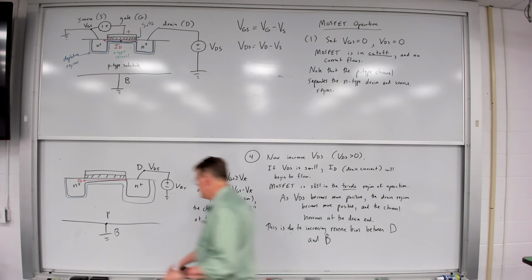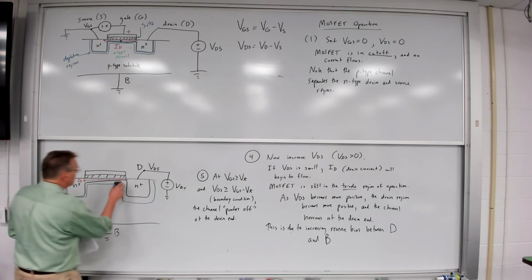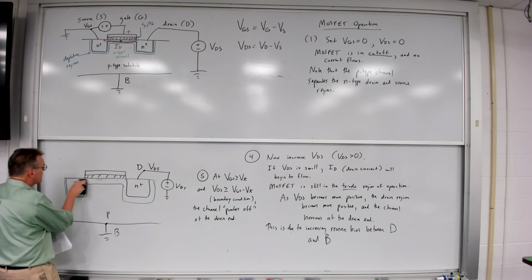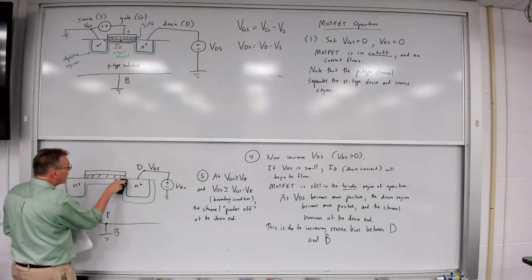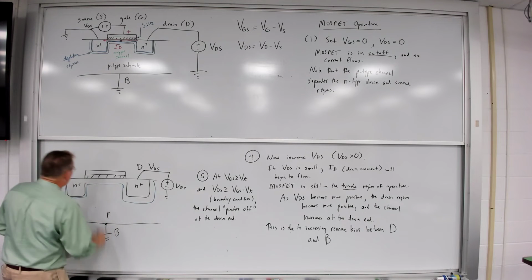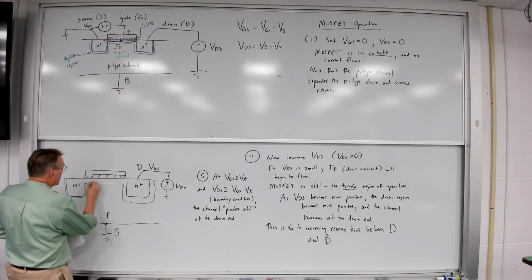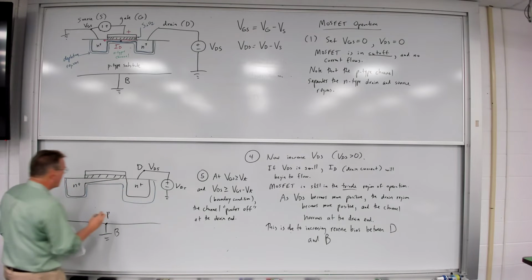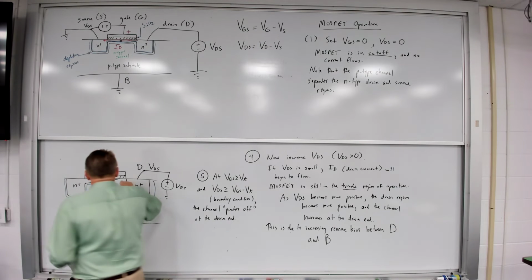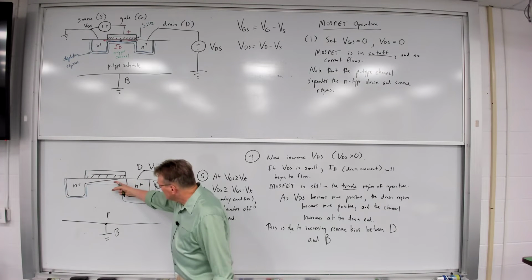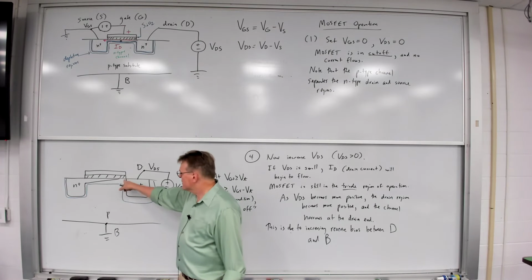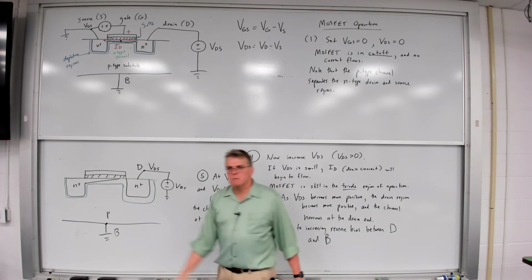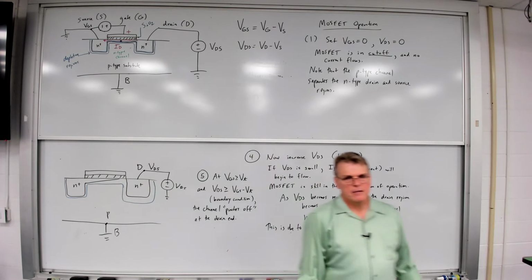So now I'm in this situation here. Now I've got this. So I get this pinch-off region where literally it pinches off completely at this end, at the drain end, once that drain becomes positive enough and the depletion region gets large enough.